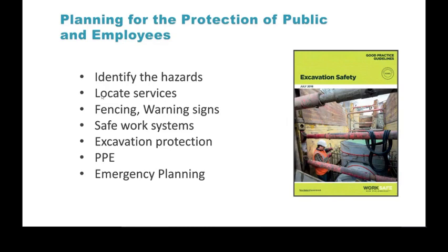So a few general things: identify the hazards, locate the services, fencing, warning signs, stuff like that, because you've got to protect yourself and the public from falling into your hole. That's a legal requirement. Having safe work systems, which is part of that communication. Who can do what, where, when, how you do things, how you lift things, how you move things.